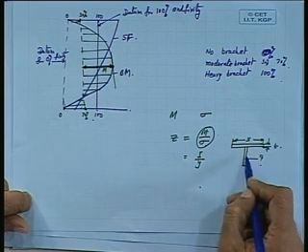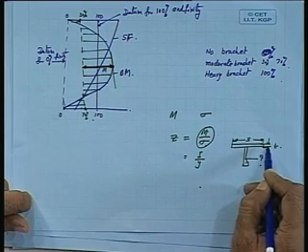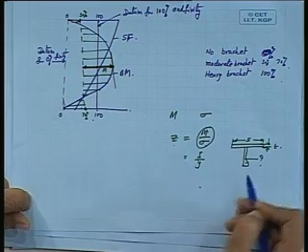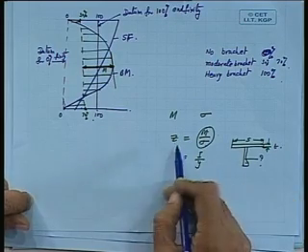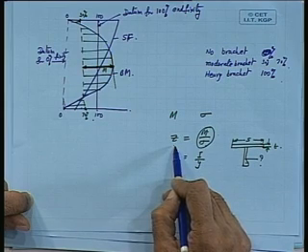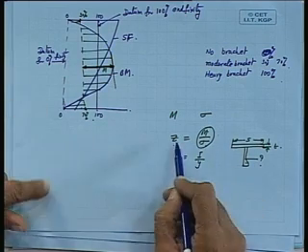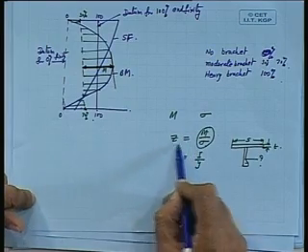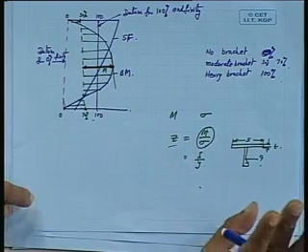You take a rolled section, add to that this particular thing, find out the section modulus and check against this required section modulus. Whatever section modulus you get should be more than this value obtained here. So, the problem will only state the minimum section modulus required. You have to calculate up to this and finish it off.